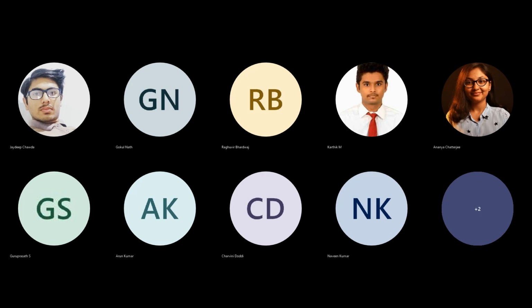You can refer to things like Fick's law of diffusion. You can say the flux is proportional to the driving force divided by the resistance, or you can say N_A is proportional to your driving force, that is dC_A, and inversely proportional to your resistance, that you can call a distance, dZ. So you introduce a proportionality constant, that is called the diffusivity of the molecule, diffusivity of one molecule in the liquid mixture. Then you extended this concept to convective mass transfer.